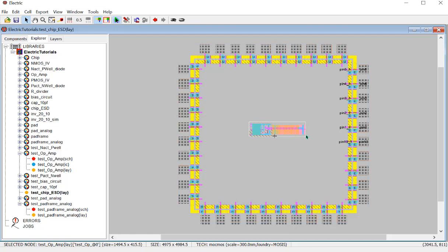So here are some tricks when you are connecting this one to these pins, because they are in the same domain, same range, and whenever you are trying to connect the wires to somewhere, you have to press Control and right click. I'm going to show you how to do it, okay? So I will do a Control J, rotate it, and Control J again, because I want to have all these ports on the top, because mainly all these pins are on the top, and I will move it closer to the pad.